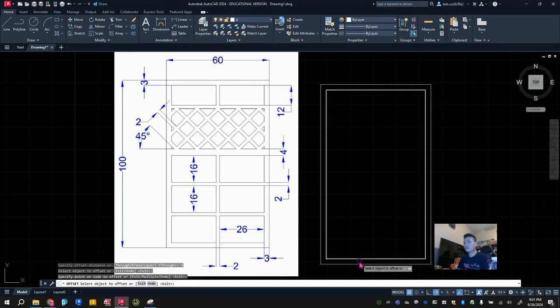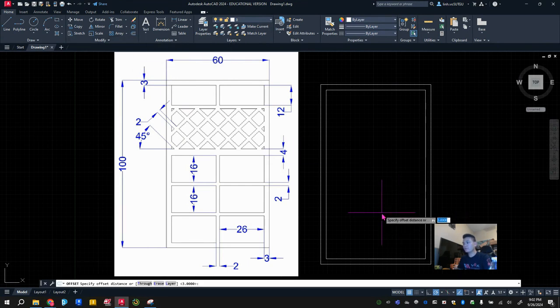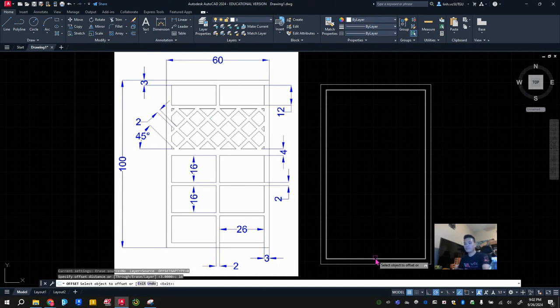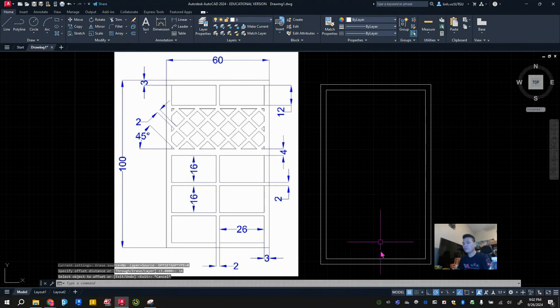We could go to rectangle to create it, but I can do this right now. I'm going to go ahead and offset. I'm going to click offset, and I'm going to offset 16 units up. Oops, there's a problem here. When I put my mouse on here, it selects the whole rectangle because I created a rectangle, right? So there's a way to do this. Click on that and hit explode.